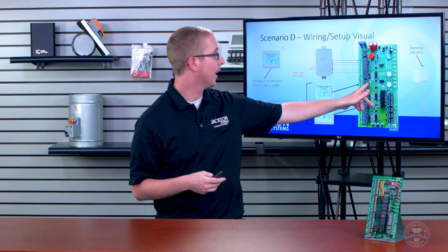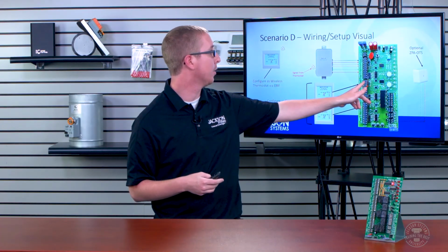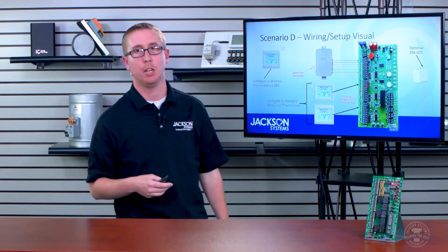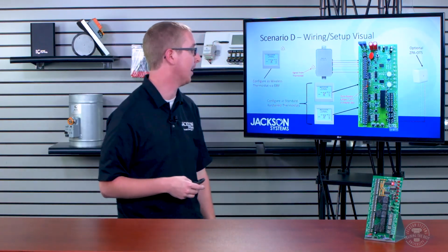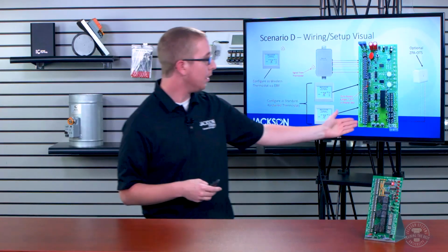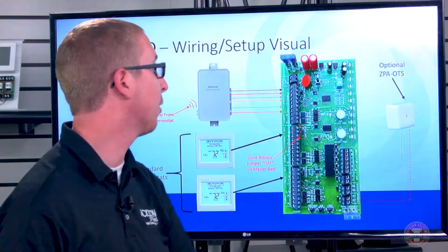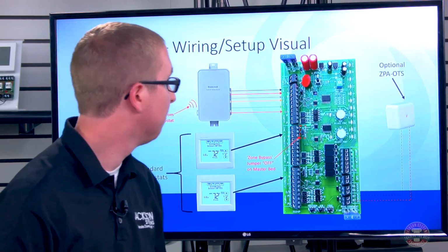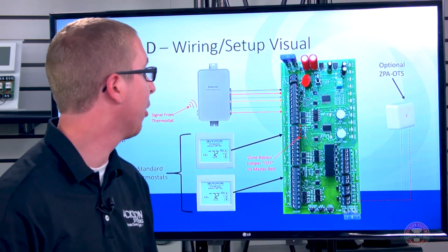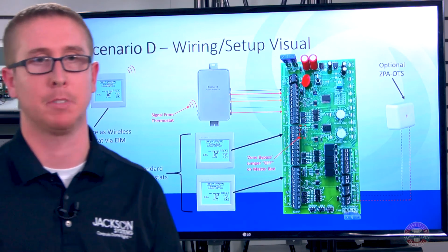Right here is a little box. That's where the jumper's located, basically adjacent to the hot and common of each zone thermostat terminal. So on zone 2, you'd make sure that jumper was in the off position. And then if you were so inclined to include an outdoor temperature sensor, it just wires right on down there. These dials are for your high and low balance point temperature settings.